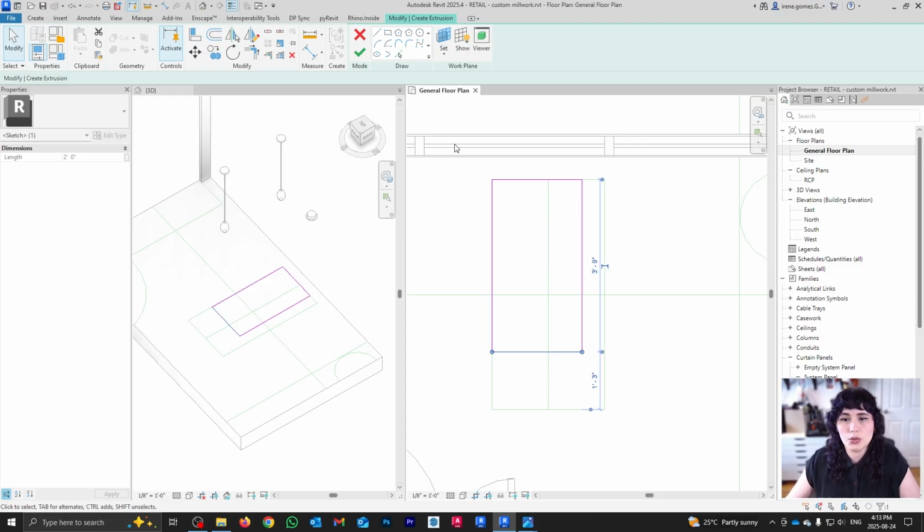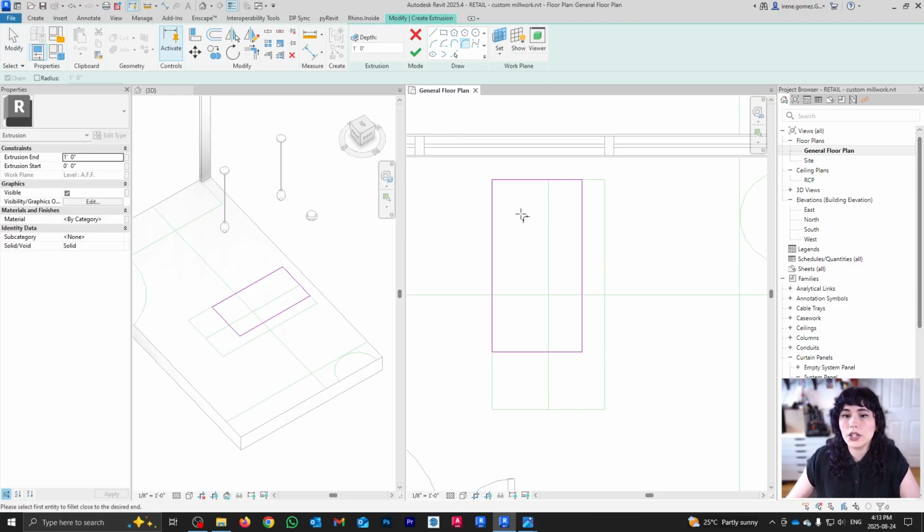And one quick and easy way that you can round your geometry is by using the fillet arc. So you can only use this if you already have 2 lines that you can fillet together. So I can click on this guy, and then I can select how big or small I want that little arc to be. Right now, it should be 12 inches because if I want it to be a perfect pill, then it has to be half of my length, we said that it was 2 feet, 600 millimeters. So if I want that perfect half circle, each of these fillets has to be half of that dimension. So that would be 12 inches, or that would be 300 millimeters.